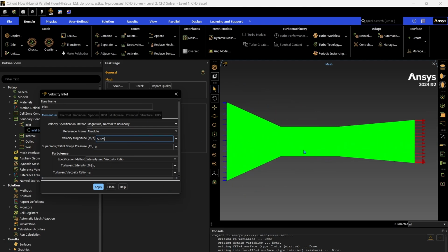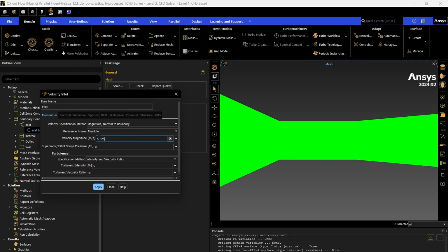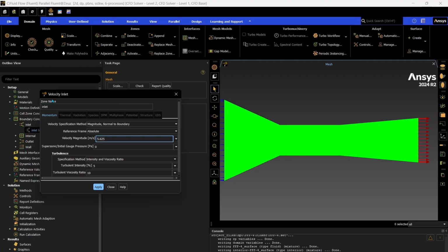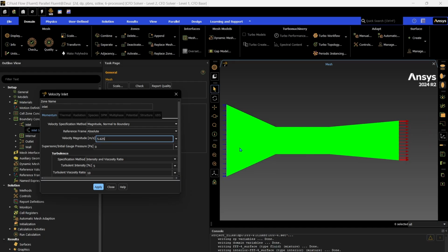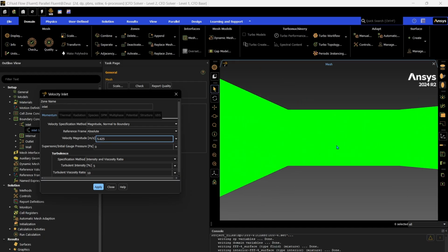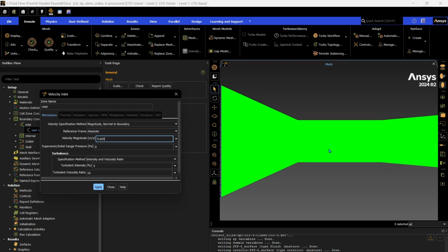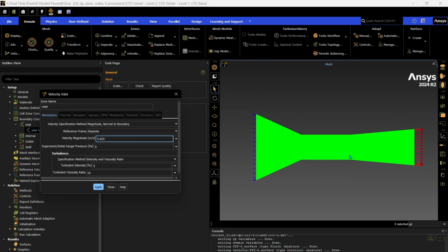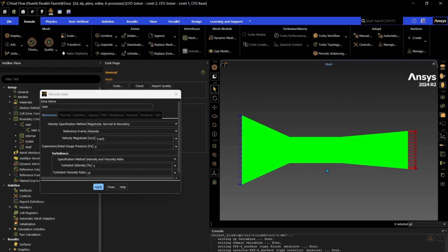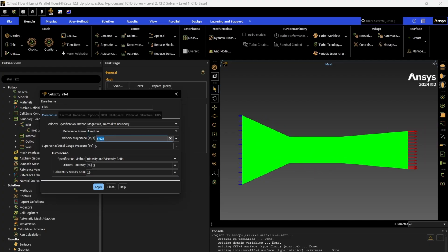Now keep in mind, yes, we have calculated the magnitude here. We are using viscous physics to simulate, so the velocity in here will not be 15 everywhere. Rather, it will be 15 close around here, maybe in the middle, closer here, but not directly in the middle. This is to be expected. Overall, the average velocity should be 15. But this is the calculated velocity magnitude that we get, so we're going to use that.